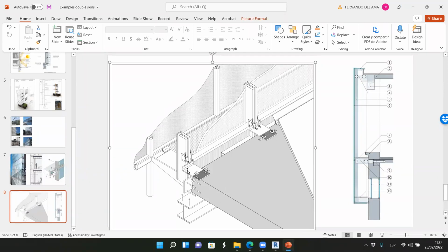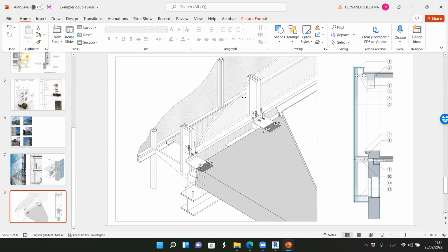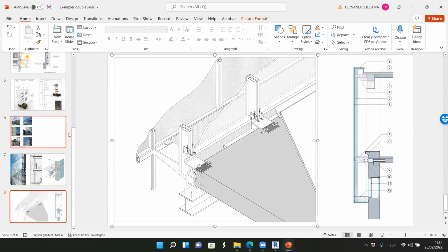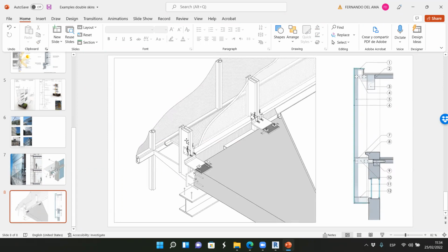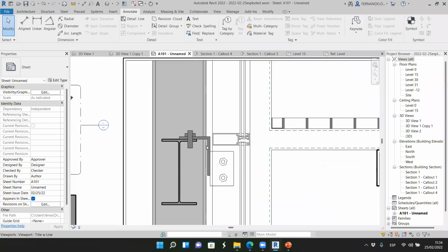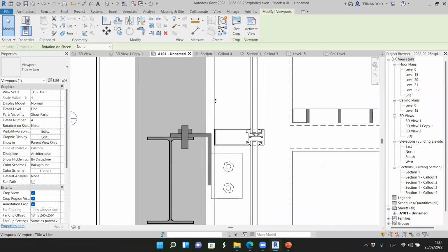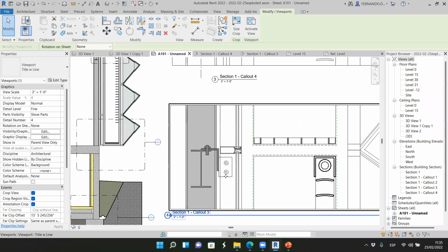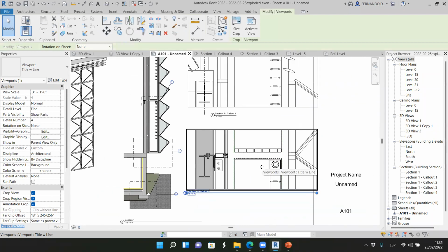We don't have to design this. It's given. If you hire a good curtain wall company, they have all these details and you can ask for these details. But I think that by doing it yourself, you can understand that if we have this structure and this mullion, we need a connection that is bolted first to the structure and then to the mullion. And that is all it takes.